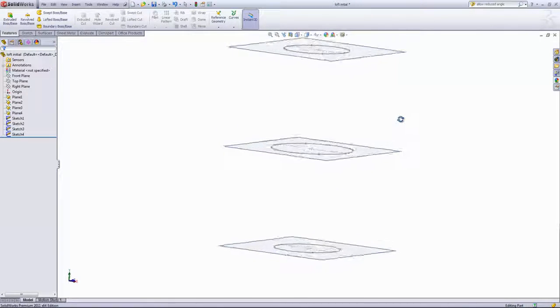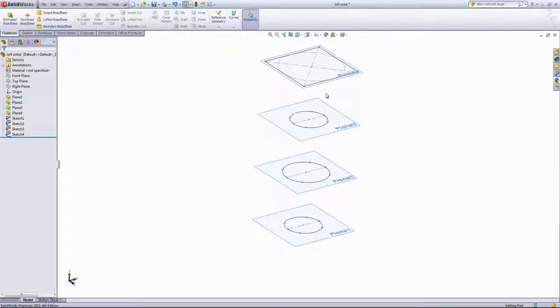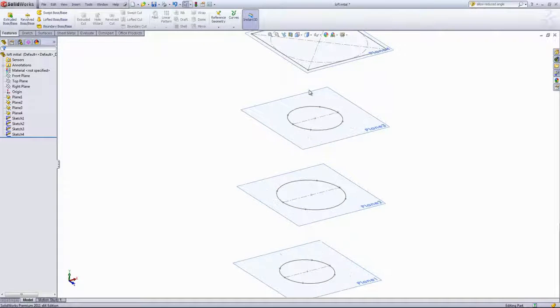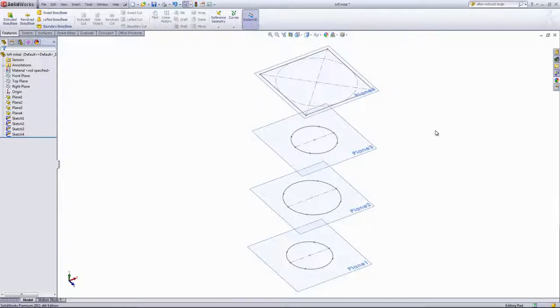Okay, now that we have all those entities split, the profile should connect itself with no problems. You may ask what happens with the points on the ends of those center lines. The loft will only see split points, so it only sees joints. It doesn't consider the center line going across a joint. So it'll just see the 4 points on each sketch.